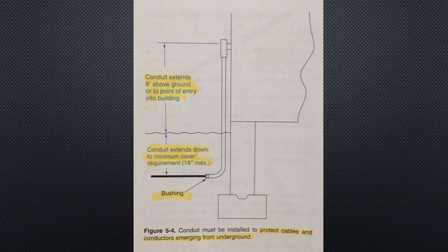Securing and supporting wiring systems. All wiring must be secured to and supported by structural members. Normally, wiring systems are not used to support other wiring systems or non-electric equipment. However, Section 300.11(B) of the Code specifies some conditions under which one raceway can be supported by another raceway.